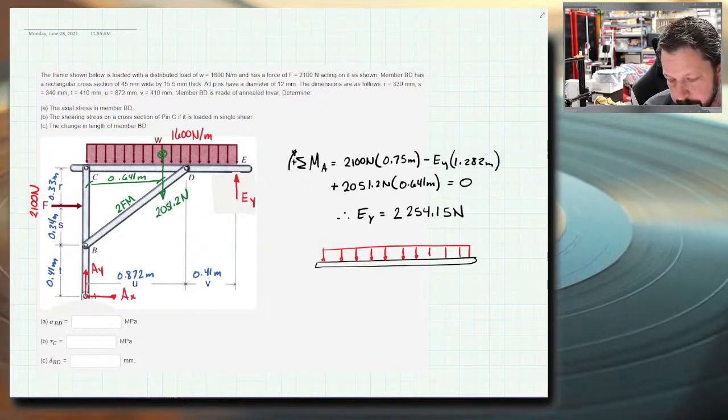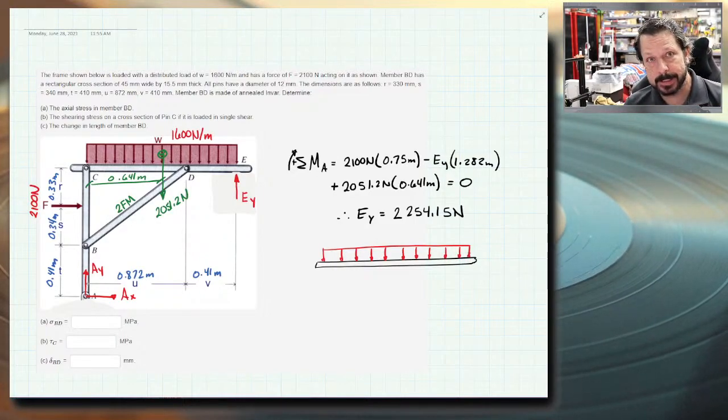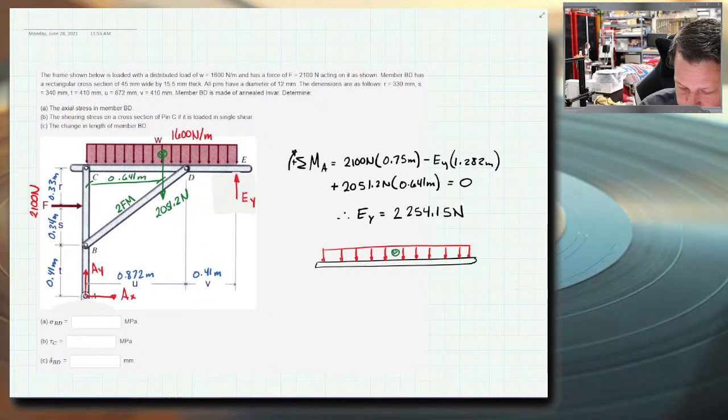But once we get into talking about whether or not these beams are deflecting, they're bending, and how much they're bending and what bending stress is in them, then it does make a difference if you treat a distributed load as a point load for flexural stress equations. So we're not there yet. So it's not going to affect what we're doing today. We could have just drawn the lumped load. I'm going to go ahead and draw the lumped load in. But in future work, it would affect it.